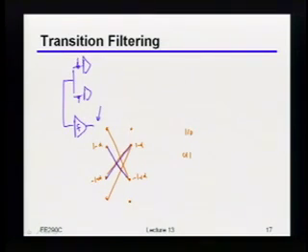By the way, I should mention that this general idea of transition filtering is not limited to loop-unrolled DFEs. There are many other applications where you might do something like this, and I'll mention one of them in a second. As another example, if you ever do multi-level signaling, for example PAM4, then you'll most likely use these transition filters. Much like what happens in this loop-unrolled DFE, depending upon which data level you're starting from and which one you're ending at, you can get very different edges, and if you just blindly use all of them, you can get very bad jitter in your clock and data recovery loop. Does this make sense to people?